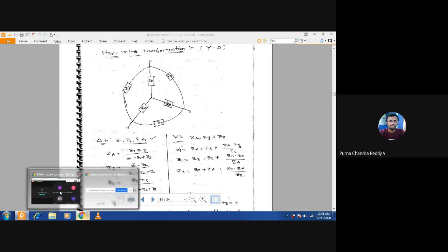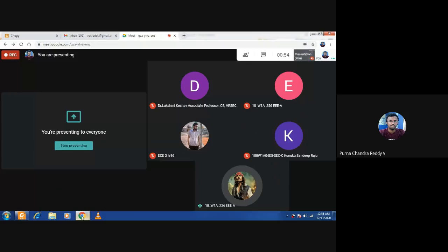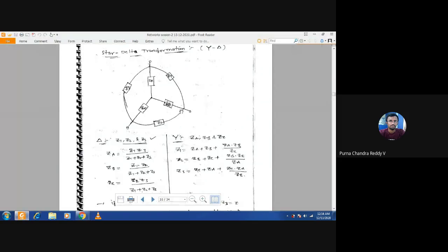So here the delta network, that is Z1, Z2, Z3, is given, and I am asking for the star network values, that is ZA, ZB, ZC. ZA is equal to Z1 Z3 divided by Z1 plus Z2 plus Z3. Now tell me, what is ZB equal to? Any of you? Please respond here. Don't sleep. Z1 Z2 by Z1 plus Z2 plus Z3. Very good. What is ZC equal to? Z2 Z3 by Z1 plus Z2 plus Z3.